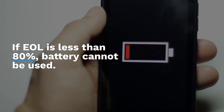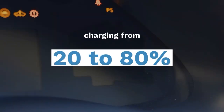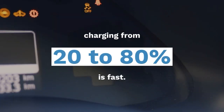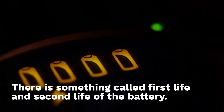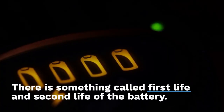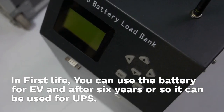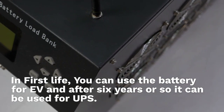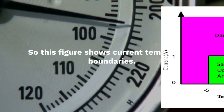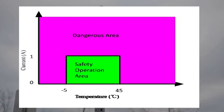If it is less than 80%, the battery cannot be used. Charging from 20 to 80% is fast, but from 80 to 100% it takes a long time. There is something called first life and second life of a battery. In first life, you can use the battery for EV, and in second life, after 6 years or so, it can be used for UPS. This figure shows current and temperature boundaries. The safe operating region is between -5 and 40.